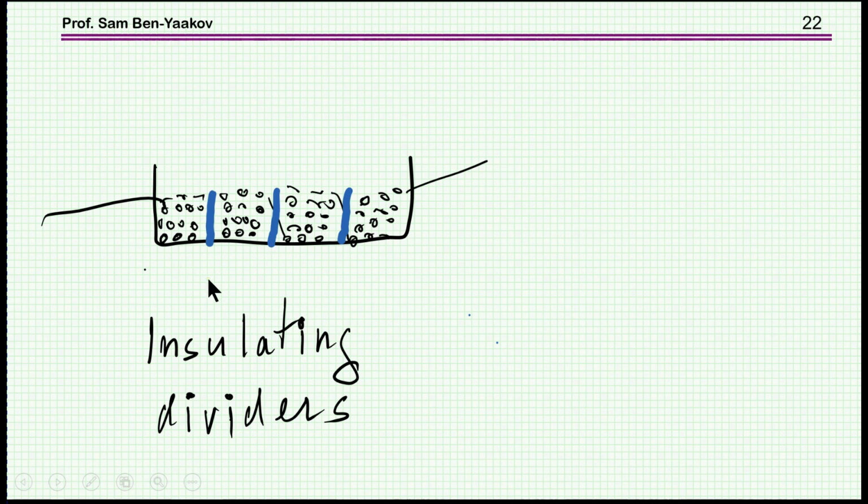First of all, the capacitance will be smaller, because you don't go all the way here, and the voltage drop is smaller here, so therefore the voltage difference is smaller here. And also, you get better insulation, because the voltage difference here is smaller than in a regular winding structure, and therefore it will maintain a higher insulation,